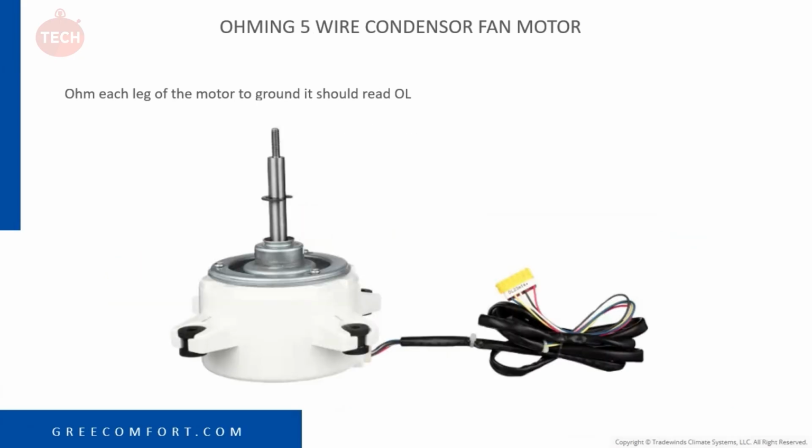Ohming the 5-wire condenser fan motor, we're not looking for equal resistance. It's not just 3 legs. So what we're going to do is ohm each leg to ground, looking for an OL reading. As long as we're getting an OL reading, that motor is not shorted.